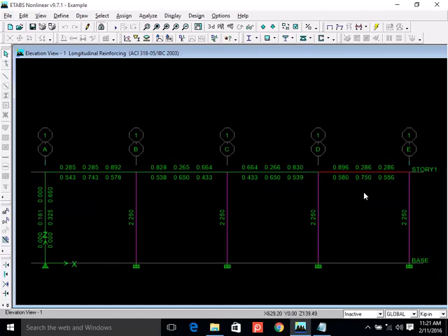And at the edges, you have negative bending moment. That's why the top reinforcement will be higher. So the three circled values are our main reinforcement. The one at the center, 0.397, is bottom reinforcement, and the two at the edges on the top are top reinforcement.